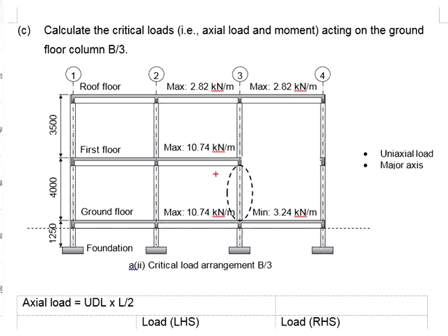Therefore, in order for you to get the moments at this end of the column, you will need to first get the fixed moments of the beam. Since you have no loads to counteract, the moment shall be taken by all three members here. Get the stiffness of the column divided by total stiffness of all the members, multiply with the fixed moment, then you get the moment taken by the column at this end. You will have another moment here.